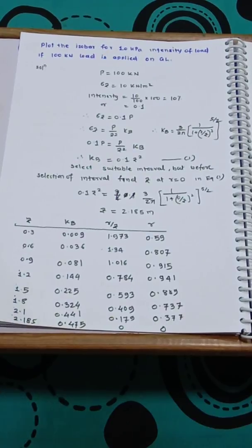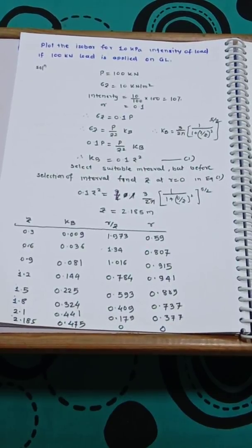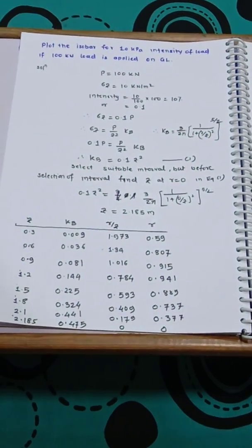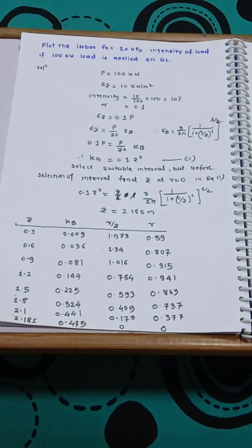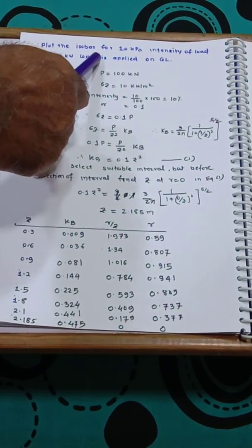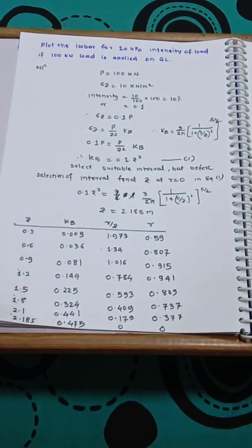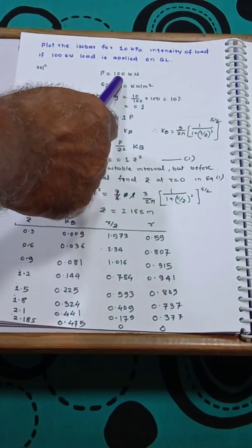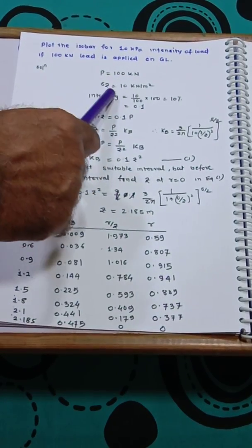We'll take a second example here. Here we'll try to plot an isobar for 100 kilopascal intensity. So the isobar I required is sigma z equal to 10 kilopascal when the load applied is 100 kilonewton at a ground level. So when a point load is applied, P is 100 kilonewton, sigma z I required is 10,